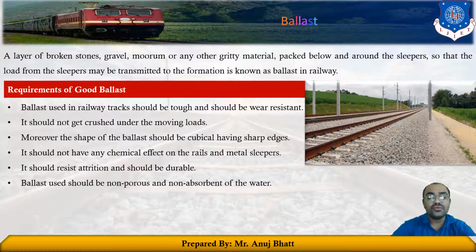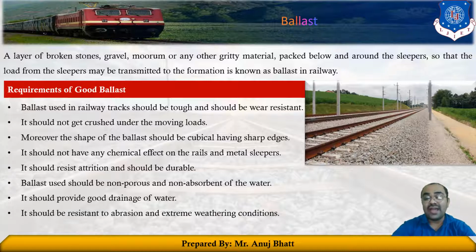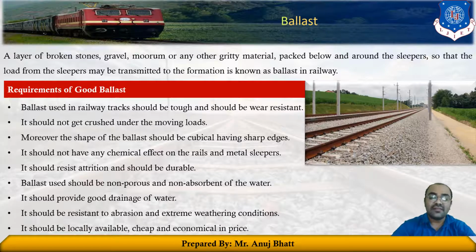The ballast used should be non-porous and non-absorbent of water. It should provide good drainage of water, and it should be resistant to abrasion and extreme weathering conditions. It should be locally available, cheap, and economical in price also. So these are some of the requirements of good ballast.